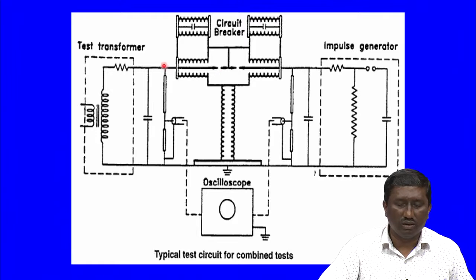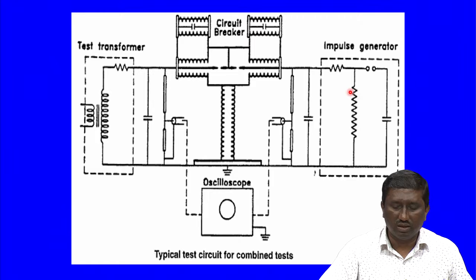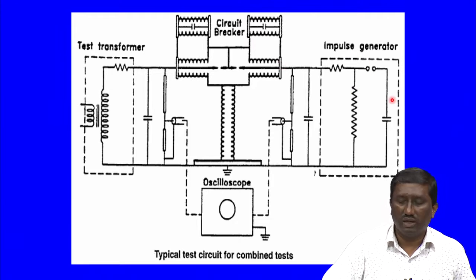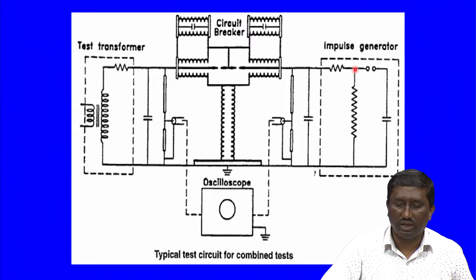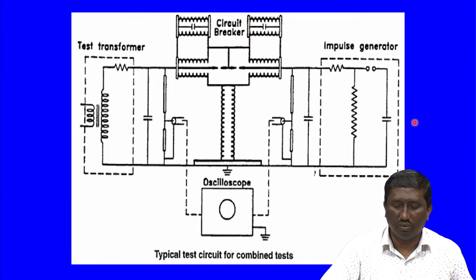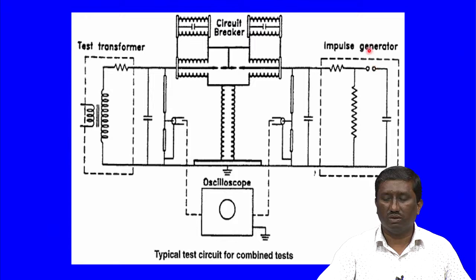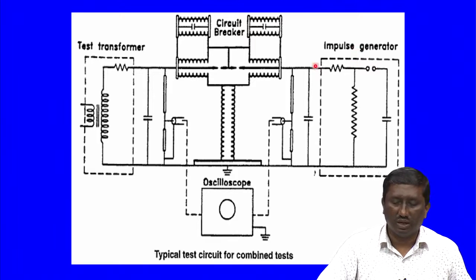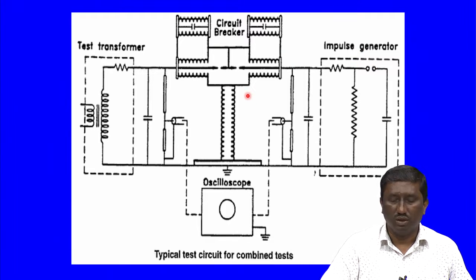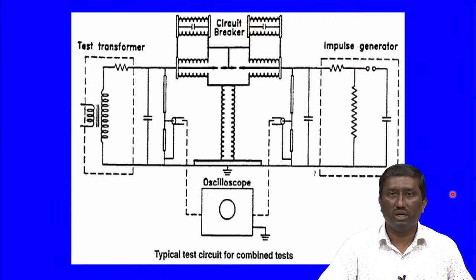At the instant the voltage is applied, superimposed on that voltage, lightning impulses from the impulse generator are applied, so that the breaker performance is tested during normal functioning connected with the AC voltage, in case surges or impulses generated because of lightning are applied. The circuit breaker is monitored and checked to verify that it could withstand this in service.